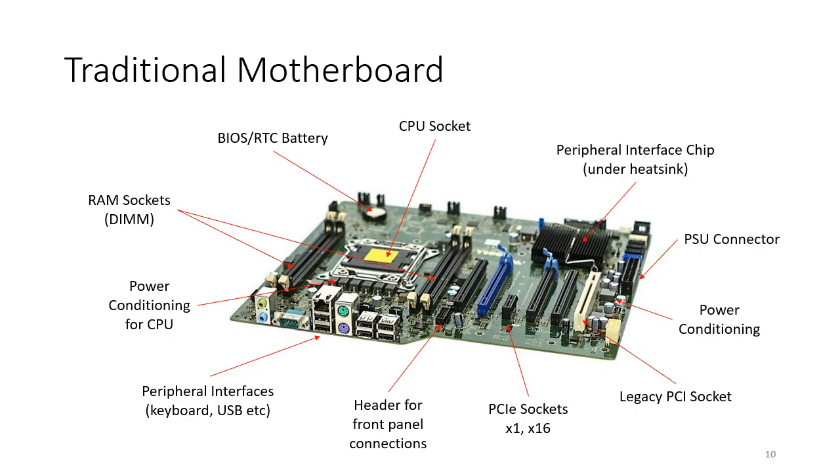So the very small PCIe slot you see there, the one that's not very long, is probably an X1 socket. So that has limited bandwidth, but that would be fine for plugging in, say, a sound card. And then on the bigger, longer ones where you've got X16, that gives you much faster bandwidth to plug in a graphics card. And in a really high-powered computer, particularly for gaming, you might have multiple graphics cards as well. So that's why there might be 2 graphics PCIe slots, as well as other slots for other reasons.